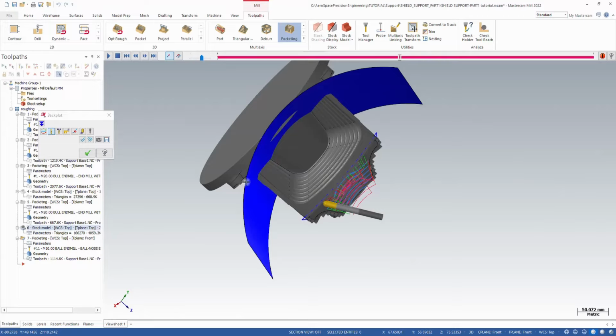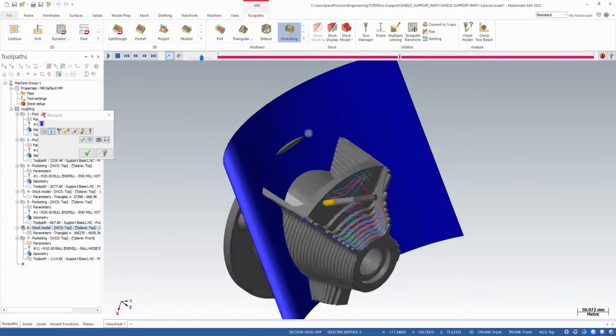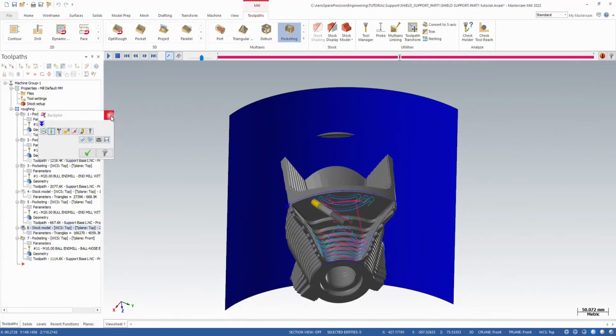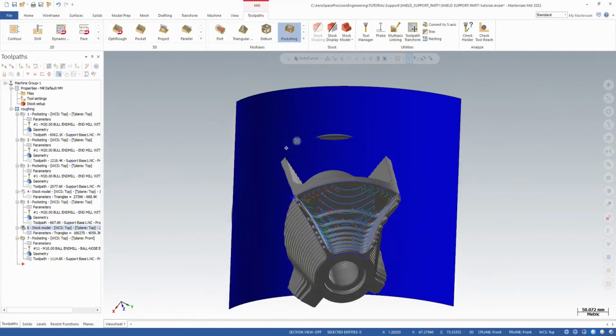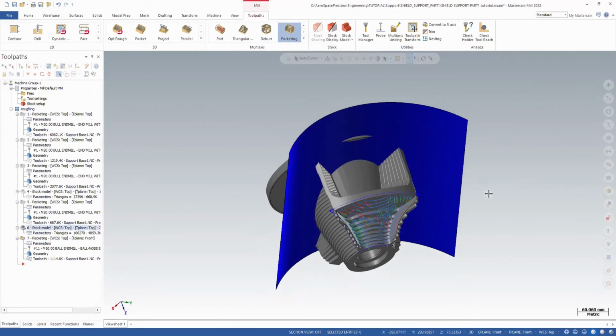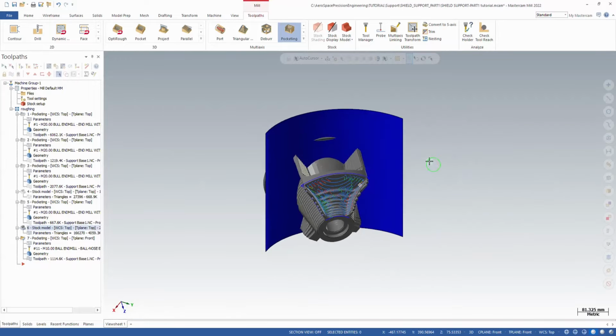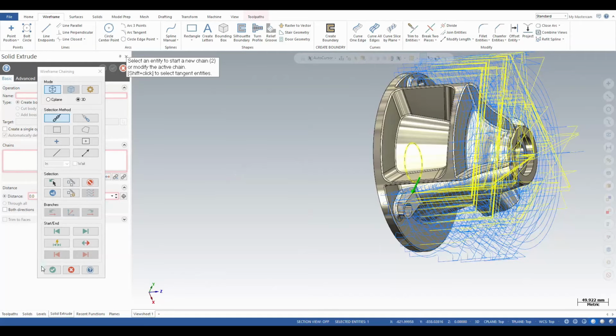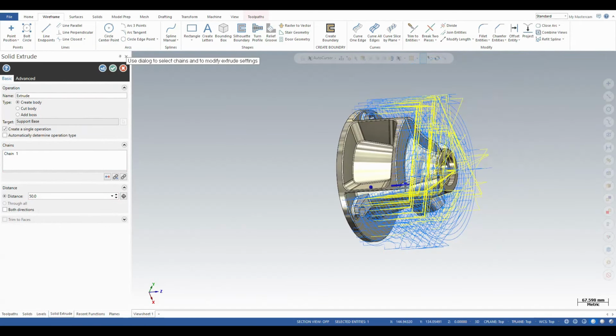Okay, so as you see, this is a very easy way how you can control the tool axis using a surface that you create behind your 3D model or behind your machining geometry, and control your tool angle during the machining or roughing. And before we finish, I wanted to show you that your false floor doesn't have to be a flat surface or curved surface.